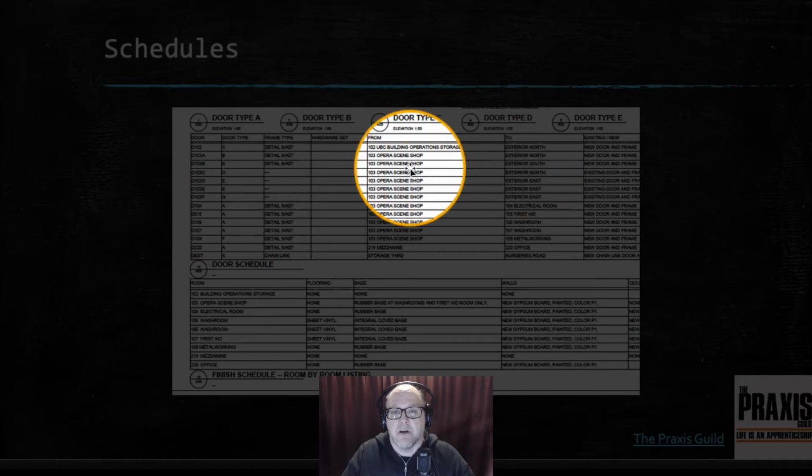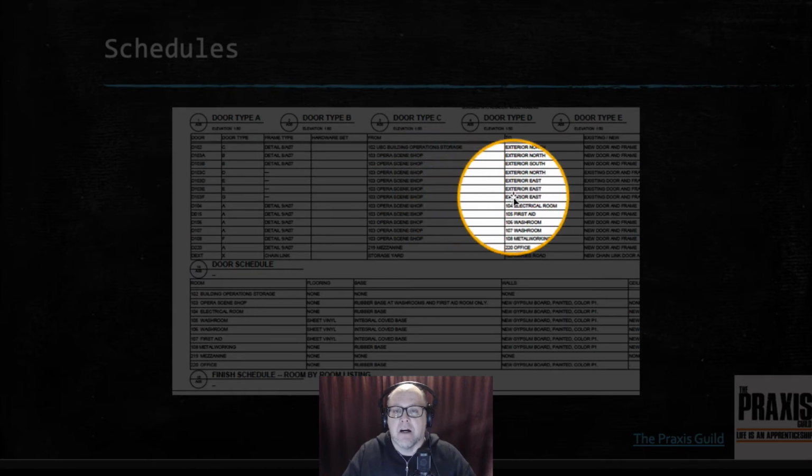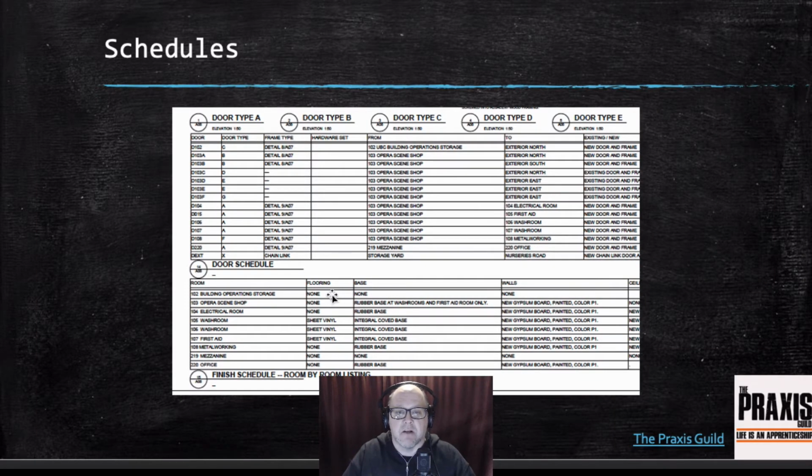They also tell you, they may also tell you where it's coming from in the sense of which part of the building you are coming out of and which part of the building you are going into when you use this door. They'll also tell you things such as what the door is made of. How many hinges will it have? What kind of hardware does it have? Does it have a window? Does it have a safety window? All these details will be listed out in the schedule.